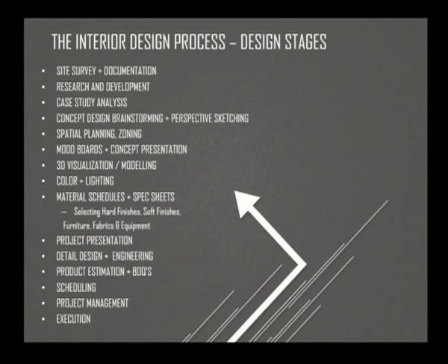So that's quite important. And next is your spatial planning and zoning. As much as you do in design and have multiple ideas, you should never quite lose track of what is important, which is the function of the given space. You might have a specific functional requirement for all of these places, and therefore you need to plan the spatial requirements accordingly. So you have zoning to do. You need to understand the movement of people within the space. You've got a specific transition from foyer to living to dining, kitchen, servant zones, served zones, private zones.